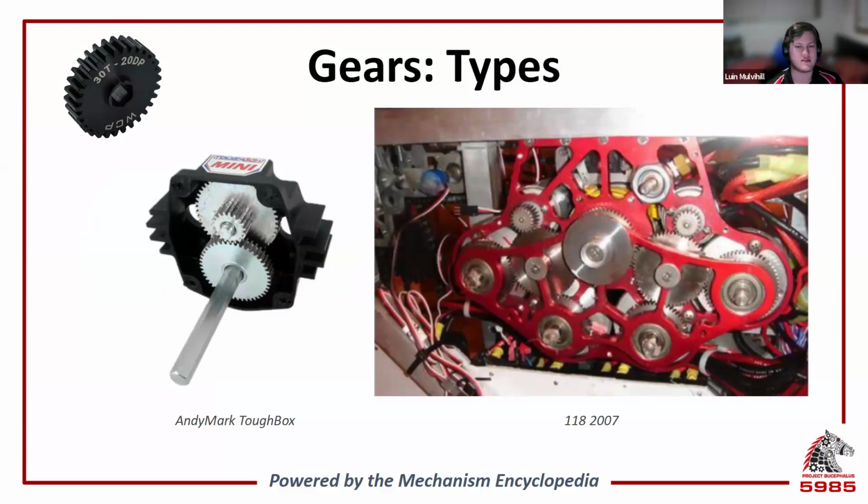As with all things that exist, spur gears have their pros and cons. They're the most efficient type of gear because they have the least contact, with only 1 to 2 teeth in contact with the next gear at any time, allowing for less energy losses to friction. However, this results in the teeth experiencing extremely high impact loading as the contact occurs suddenly and all at once. This means lower durability and higher noise and vibration.